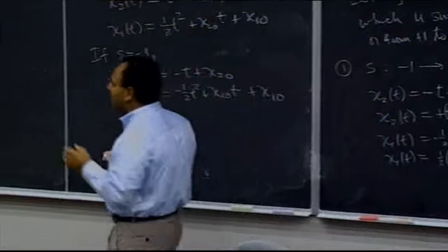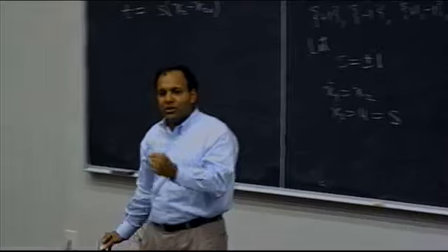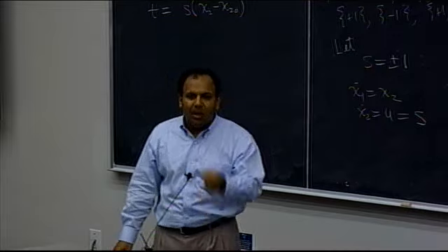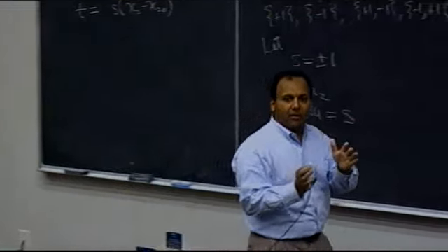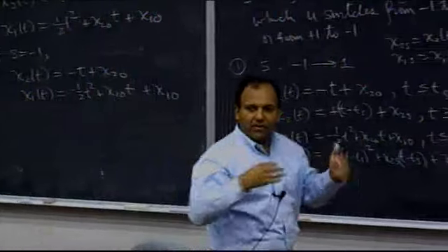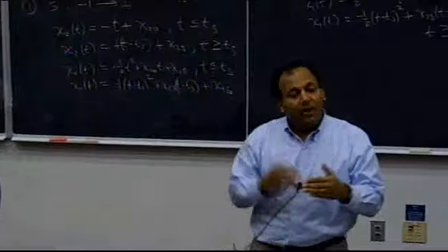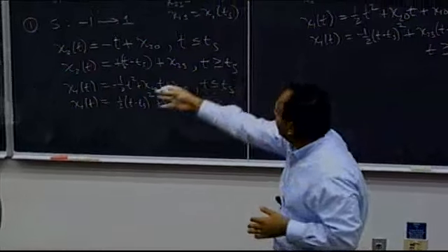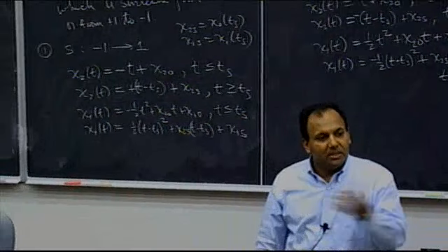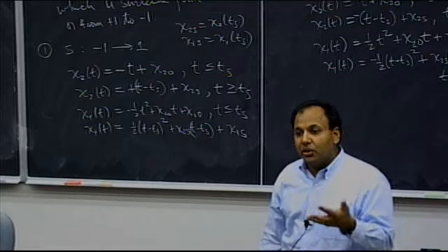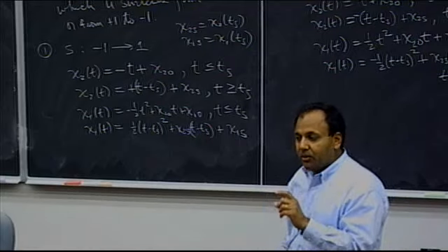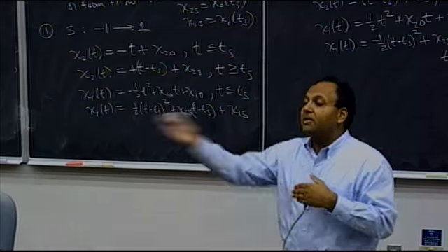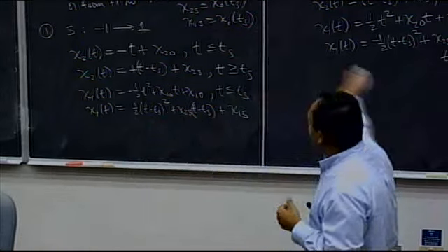The only thing that's happening is I'm imposing this cost function that says that the optimal control is the one that has to minimize the time, and I have a bounded control effort. I cannot have an infinite amount of control. I have a finite amount of control effort. That's the key. Because you're trying to minimize time, you get a problem where the Hamiltonian is linear in the control. dH/du, which is the condition you would apply if you were solving for a control on the interior of the allowable control set, isn't a valid condition to get you the optimal control. You have to apply Pontryagin's minimum principle.